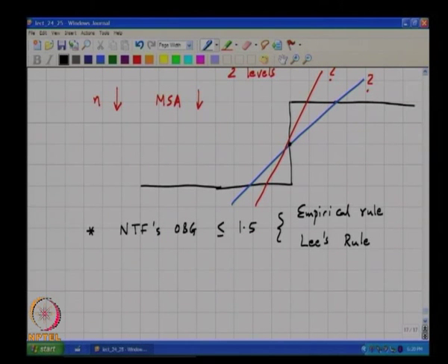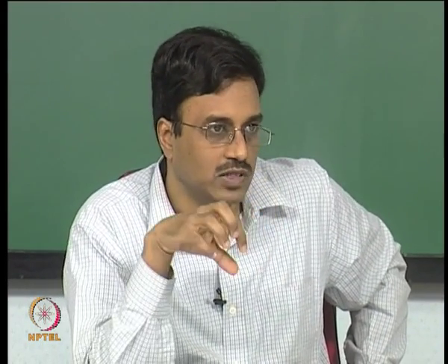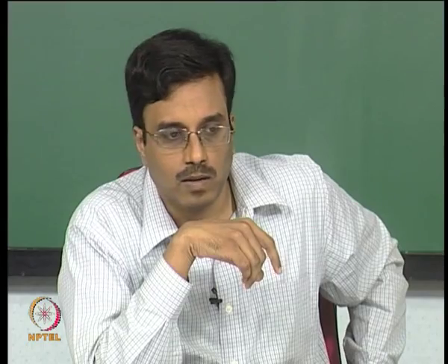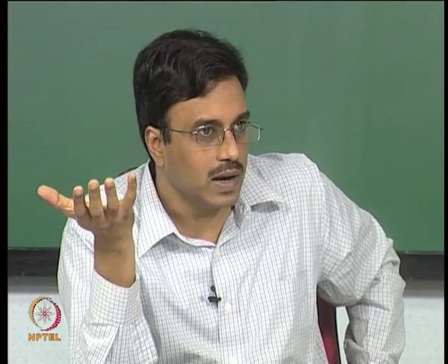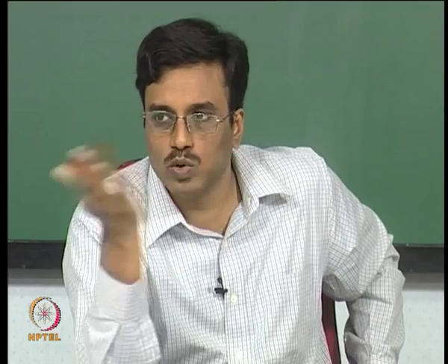So, if from the point of view of implementation of the quantizer you decide to do a single bit quantizer, then you start off, I mean there is no iterating, right. You have the order, you have the out of band gain, you choose Butterworth or a Butterworth with a passband with complex zeros, right. You compute the in-band SQNR, alright. It either meets your spec or it does not meet your spec, and if it meets your spec you are done. If it does not meet your spec, the only thing you can do is increase.